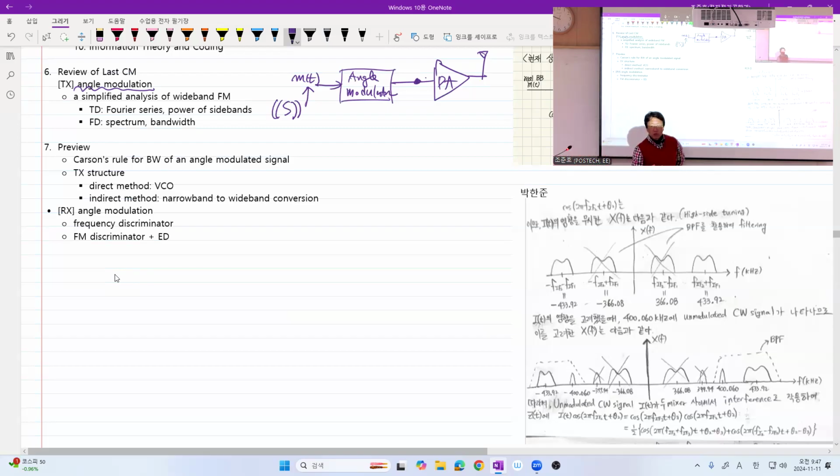Of course, in some cases, you have to think first about the constant signal. Sometimes zero signal, but in our case, zero signal means nothing. Constant signal also means not much. That's why we have chosen some other signal, which is, in this case, single tone. Sometimes we call the signal single tone or a continuous wave. And be careful, the term CW means a different thing in radar engineering or in the context of even the communication system. So single tone means a sinusoidal signal. Of course, here we are studying the early times of communication technology, so all the message signals are real baseband signals. However, in digital communications, most of the message signals will be complex baseband signals. Anyway, so here, real baseband single tone.